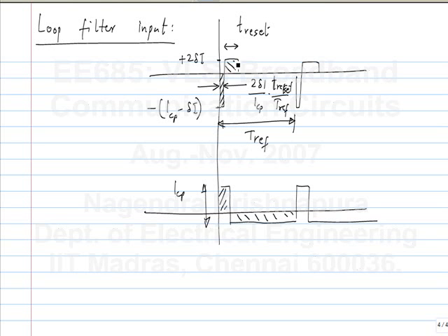Whereas here it is related to the mismatch. If the mismatch becomes smaller, you get much better results. The phase shift itself is related to mismatch, and the area of this is related to the mismatch. So, there will be reference feed through, it is not 0, but it is much smaller than in the type 1 PLL. Okay. And of course, we can put additional poles to further filter it if necessary.